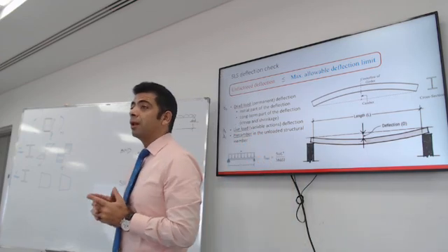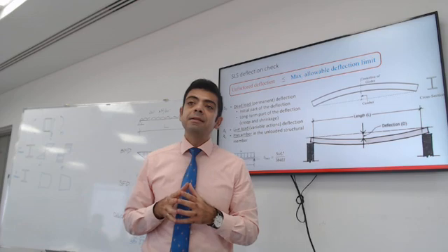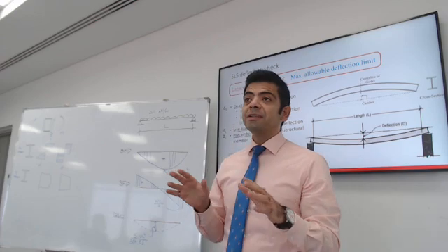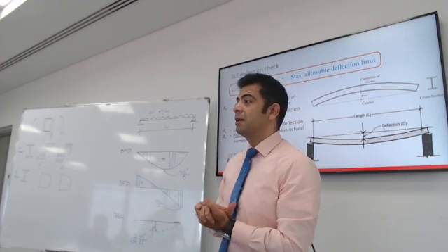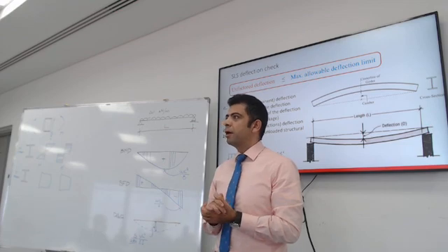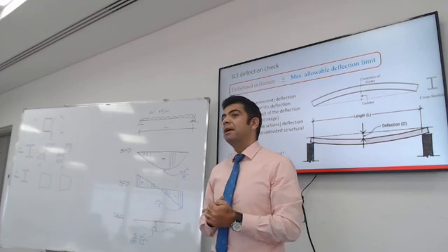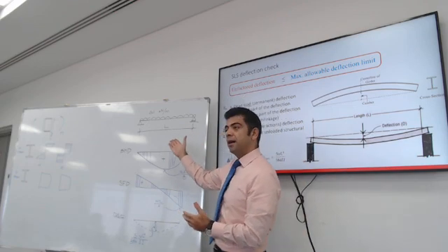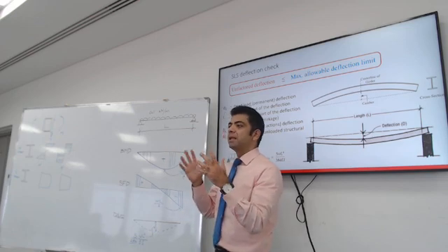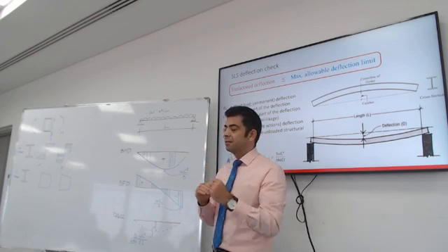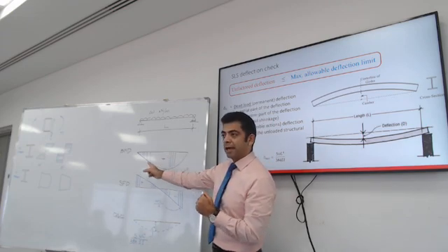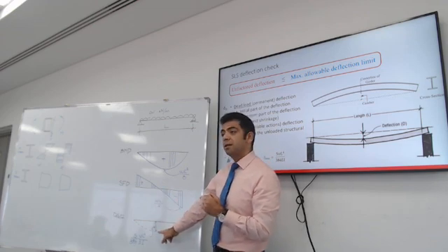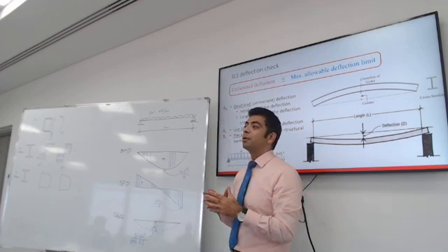Hello and welcome to the third lecture in this design module. Today we are going to conclude the design of beams. And this is something that we've been talking about over the past couple of weeks. And the process is as follows. To finish the design of a beam, you need to do mainly three separate checks. Design the beam for flexure, for bending, design for shear, and check the deflection is not exceeding the allowable limit.